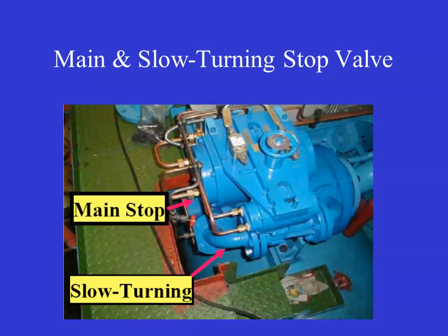If you were going to go into the interior of the engine and work, you've got to make sure that your start air is secured. In the case of the main engine, you don't want to get an accidental start while you're up against the dock, so you're going to block air to the engine to prevent an accidental start, and these act as a block valve.